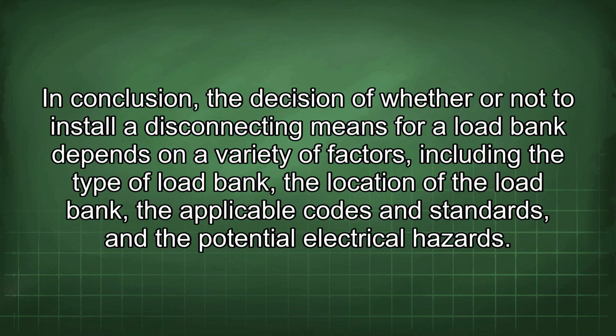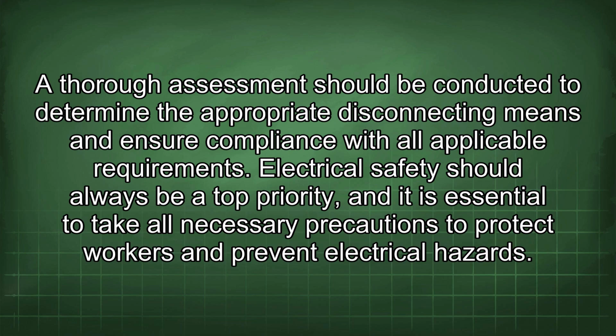In conclusion, the decision of whether or not to install a disconnecting means for a load bank depends on a variety of factors, including the type of load bank, the location of the load bank, the applicable codes and standards, and the potential electrical hazards. A thorough assessment should be conducted to determine the appropriate disconnecting means and ensure compliance with all applicable requirements.